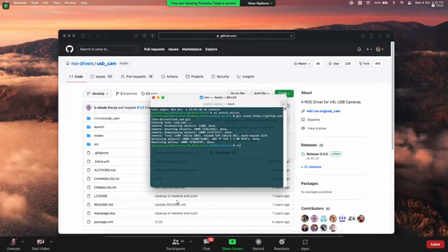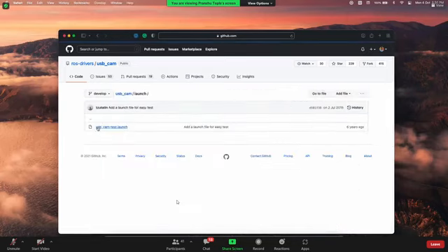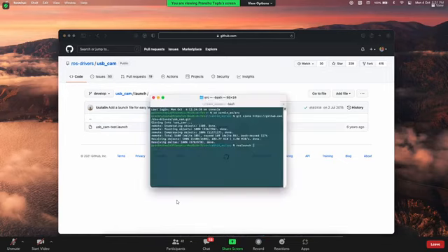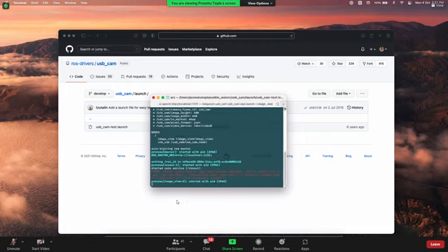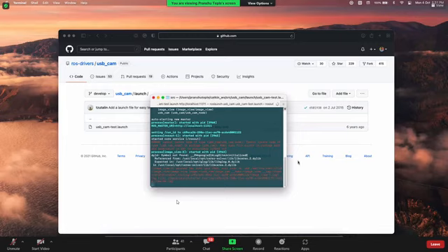Now what I will do is simply launch the launch file, which is roslaunch, the name of the package, which is usb_cam, and the name of the launch file. Cannot launch node of type usb_cam: cannot locate node in package usb_cam, make sure file exists. Okay, so maybe it is not executable.